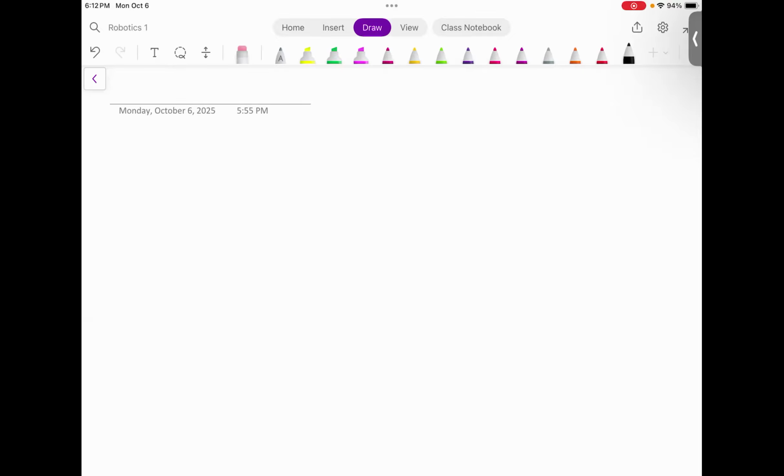Okay, so I'm going to draw the SCARA robot. When you go to the lab, I can show you how an actual SCARA robot looks. The DoBot that you have played with is an R perpendicular R, parallel R type of robot. If you look at the SCARA robot, there are two configurations possible. One classic configuration for the SCARA robot is something like this.